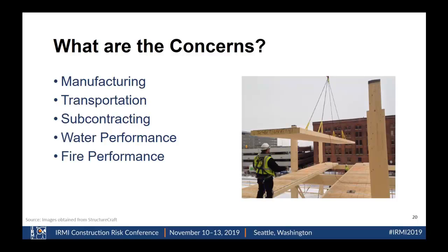Fire performance, obviously wood will burn. They oversize the members in order to account for burn rates. So your 1 hour, 2 hour rated assemblies are taken into consideration. It's not only designed for structural, but it's designed for structural being able to sustain through a fire event.